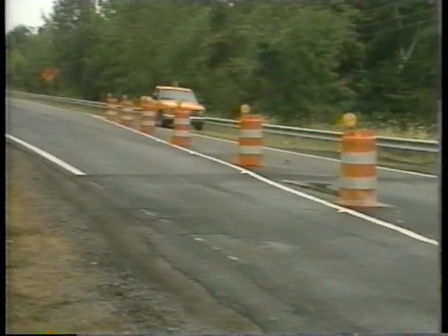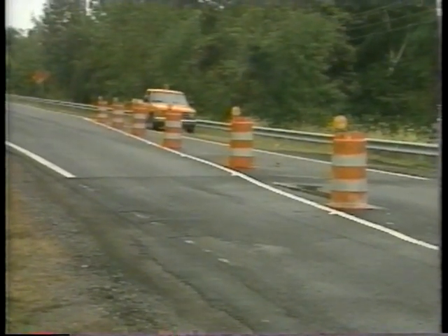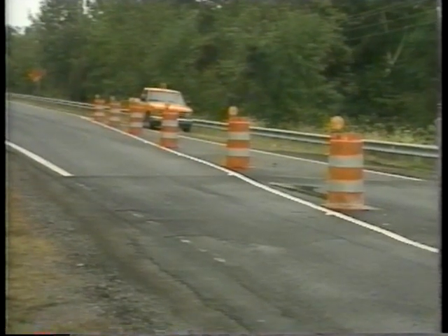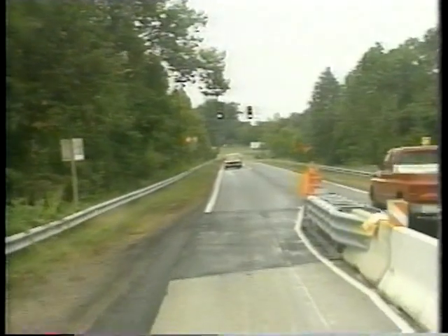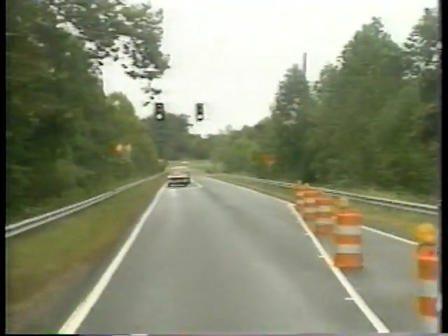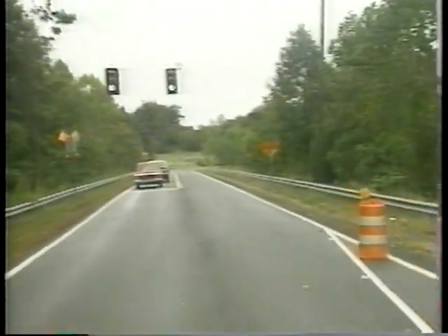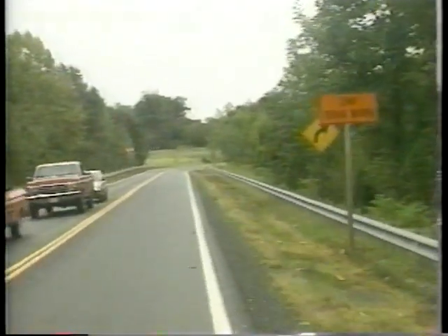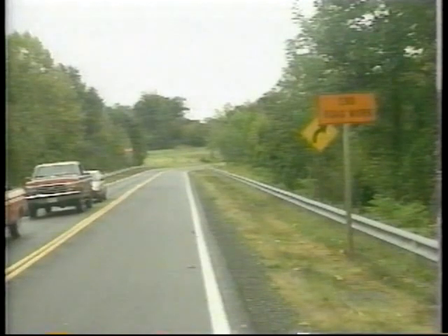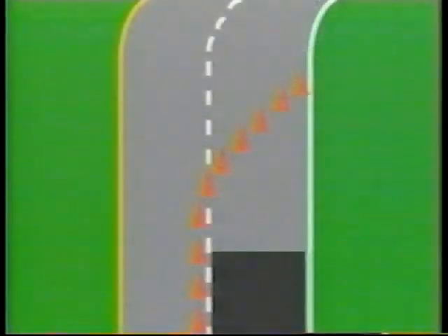The termination area provides a short distance for traffic to clear the work area and return to the normal traffic lanes. This area begins at the downstream end of the work area and goes until there is an end construction or end roadwork sign. Normally, the termination area has a reverse taper guiding traffic back to its normal path.